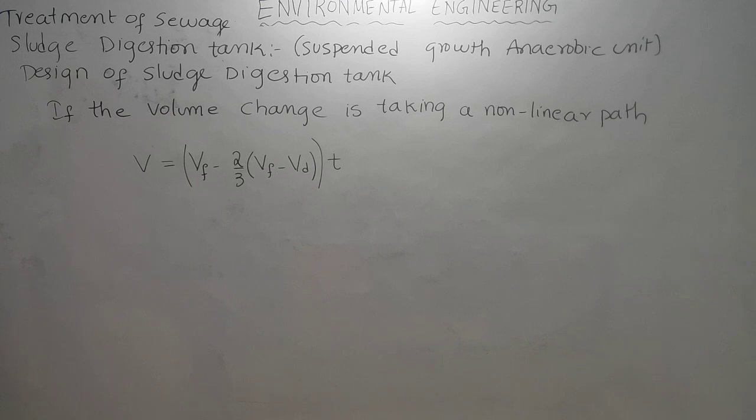And again here, sometimes we also have flood water like storm water. During the flooding seasons it is not possible to withdraw the digested sludge because the sludge drying bed will be flooded. That is why storage needs to be kept inside the digestion tank during the monsoon period.